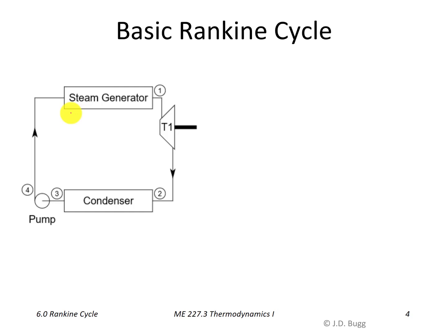Adding heat to the cycle. The biggest difference is the compressor is gone and we now just have a pump here. So we'll come out of the condenser as a liquid into the pump and be pressurized from the condenser pressure to the steam generator pressure in a pump instead of in a compressor.